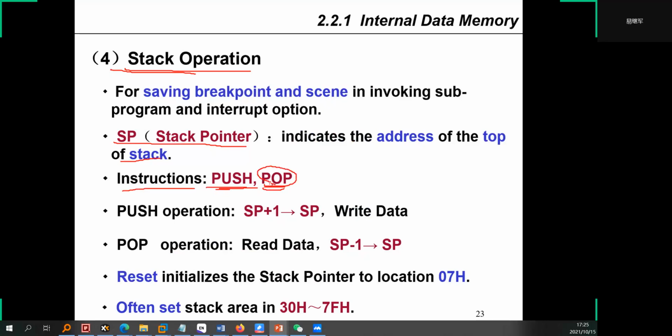Push operation: SP adds one to SP, then writes data. Pop operation: read data, and SP subtracts one from SP.